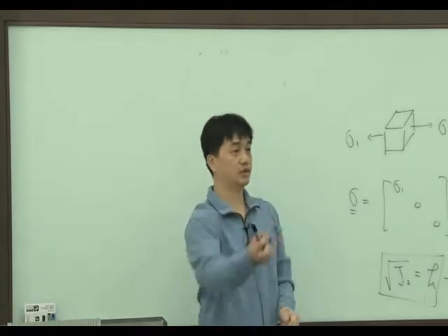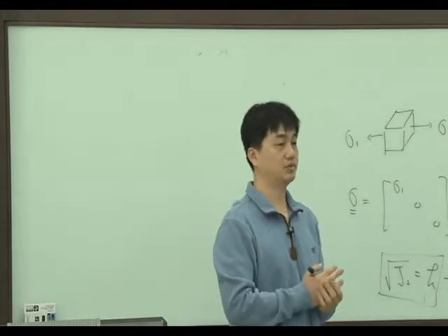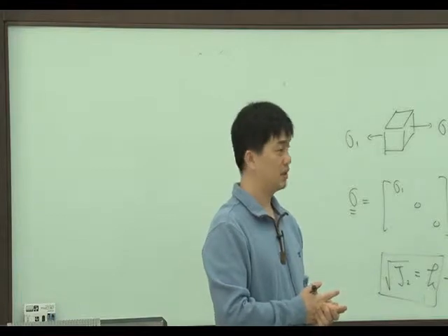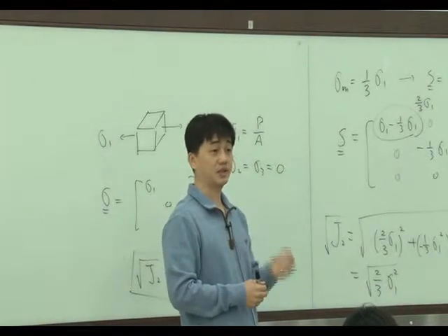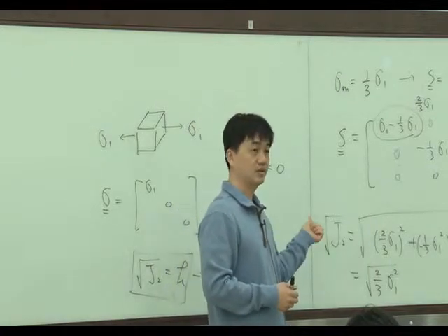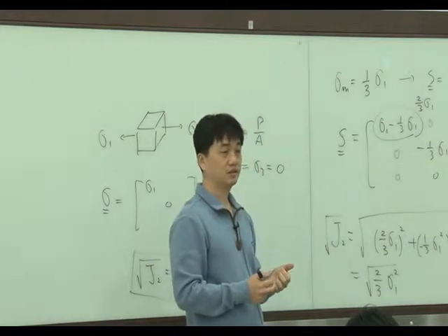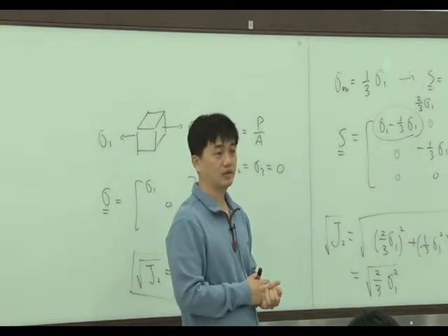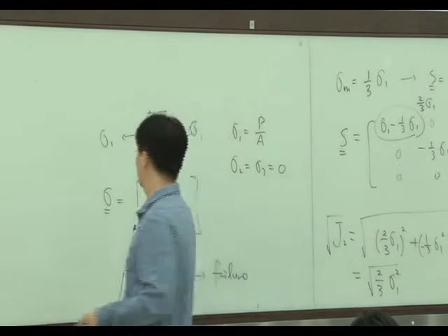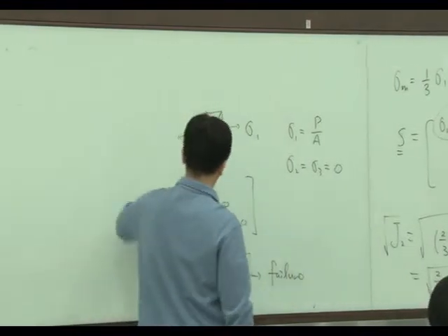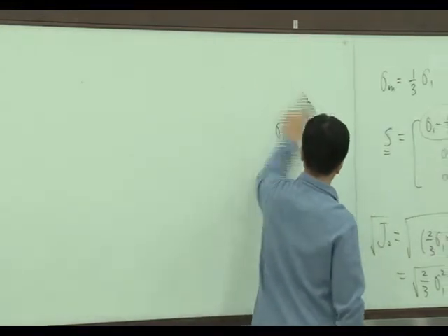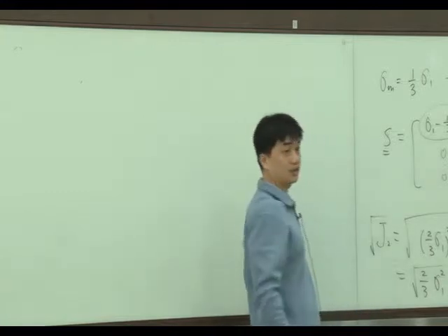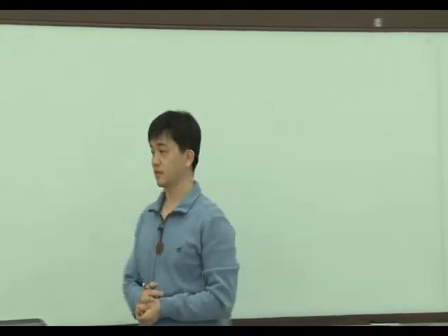In finite element analysis, the software gives effective stress, right? That effective stress means this J2. So if you compare that effective stress with the strength, here the K, we can find whether material failure happens or not, right? So you should know that the effective stress is J2.